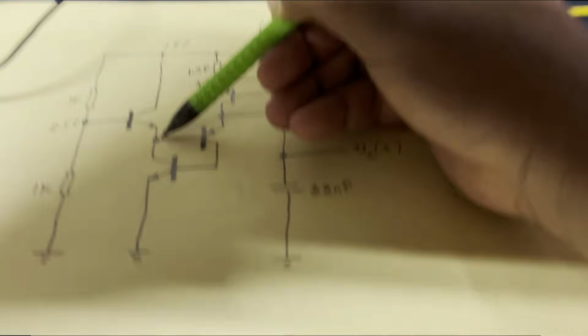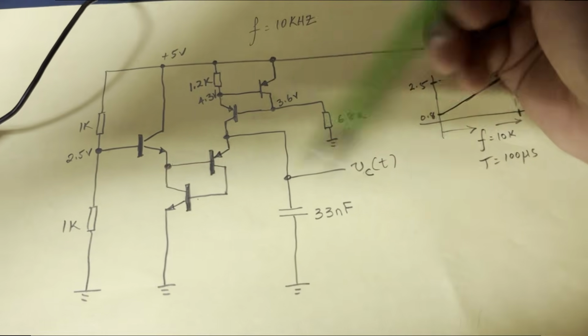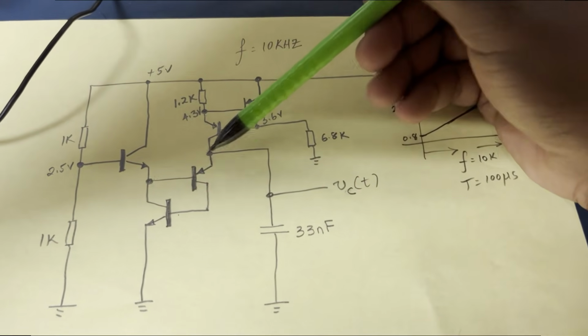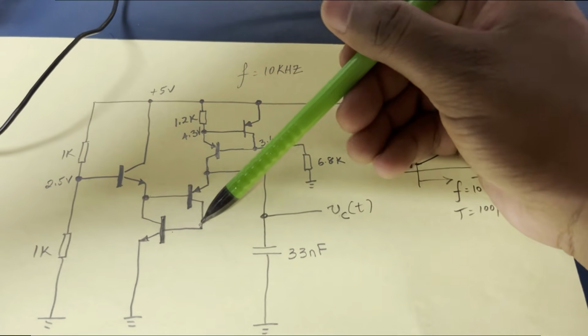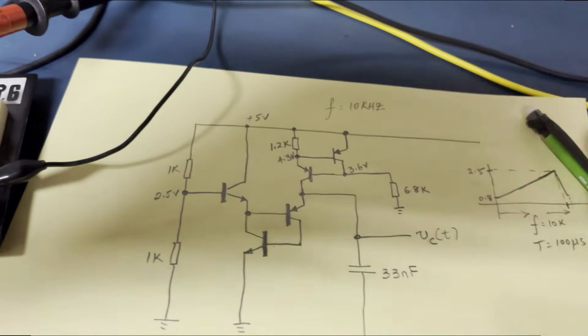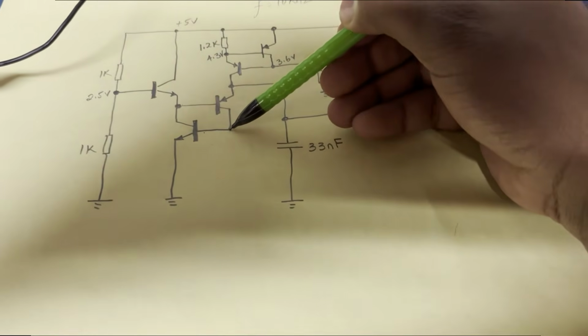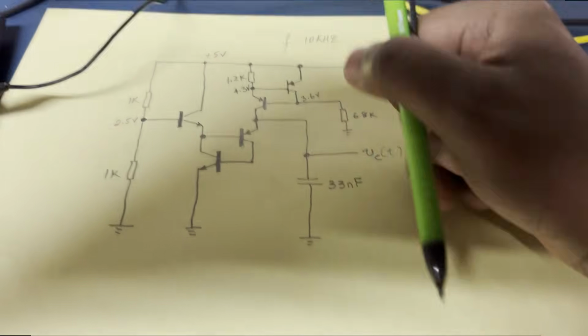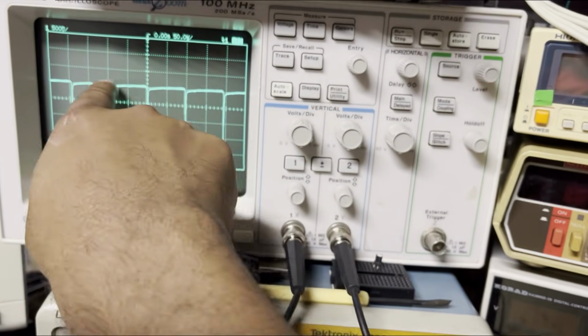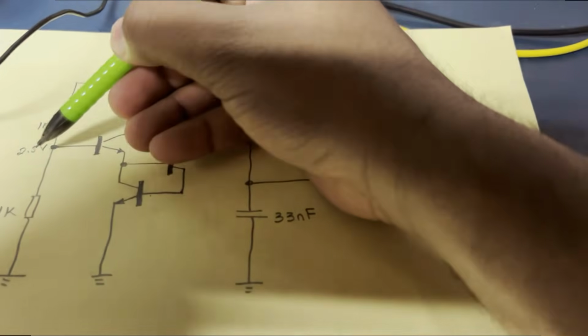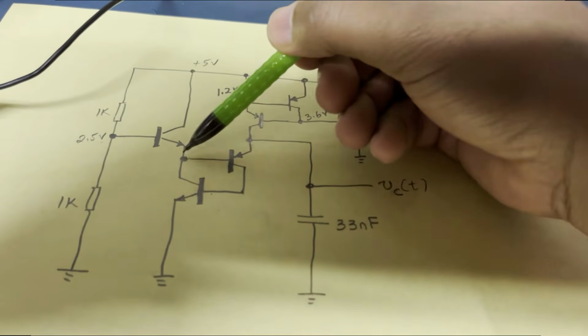That's one interesting waveform that we see at this point here. What other interesting waveform can we see? Well, we can see this guy here. That guy will be similar to this guy as well, right? It's going to be mostly about 0.7 volts, right? By the way, that voltage you can see is a diode drop below the 2.5 volts, right?